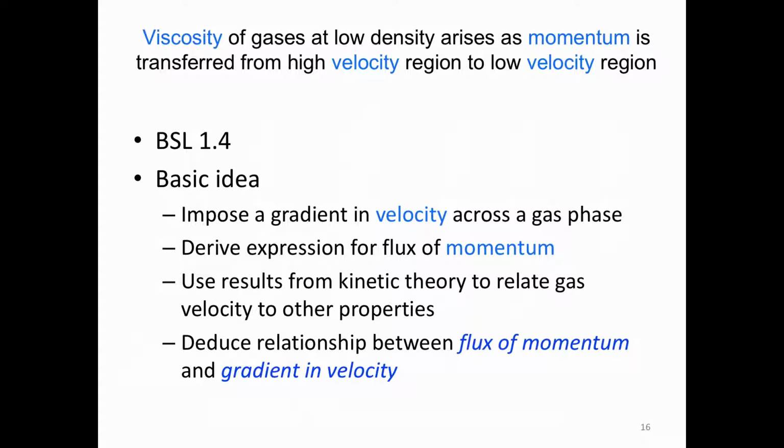When we looked at the viscosity of gases, we looked at the fundamental theory to try to explain this phenomenon. This was covered in our chapter 1.4. The basic idea was to look at a bunch of molecules that are moving around. Those molecules can have only elastic collisions, because those are relatively easy to account for. And we're not looking at any intermolecular forces, which we know are actually quite important for realistic behavior, especially as gases get more dense and molecules get closer.